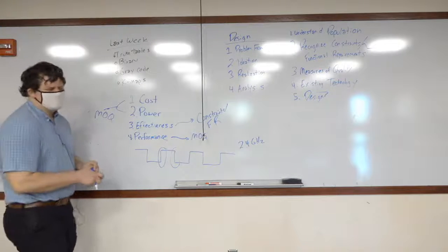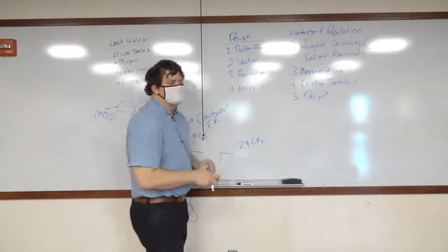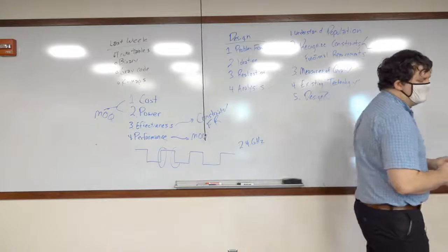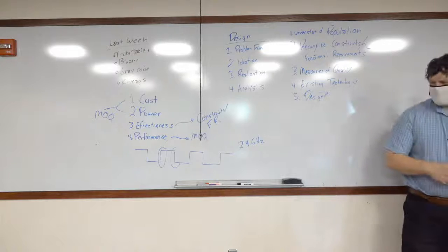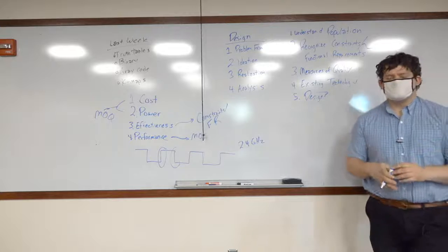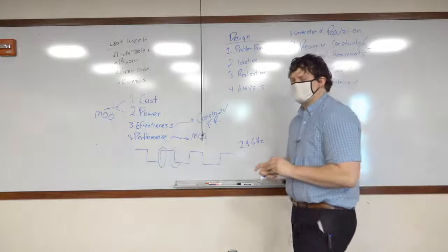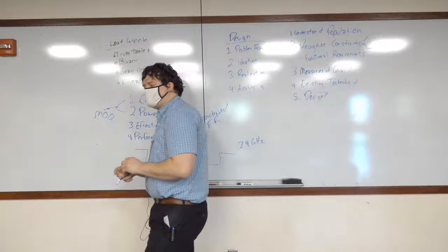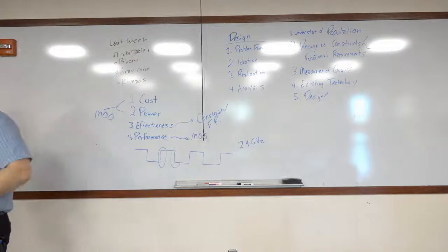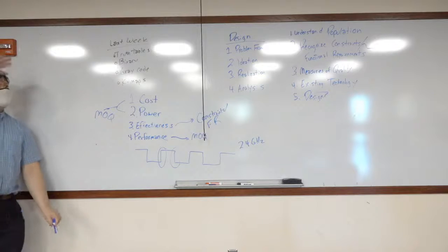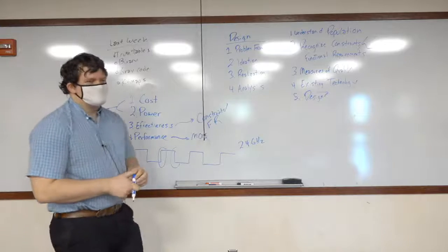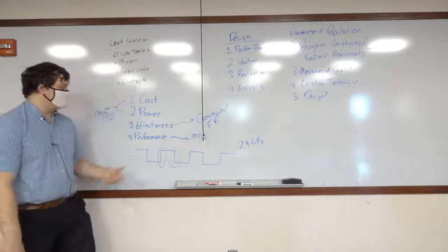If you've done any really in-depth research on IoT, which by the way is your homework for next week for the design problem, IoT systems require really low power consumption, oftentimes because they're put in remote situations. A lot of IoT systems will brag about the fact that they run off these little button batteries and they have a lifespan of 2 years before you have to replace them. Okay, IoT systems do require lower power, and you do have to reduce the clocking speed.